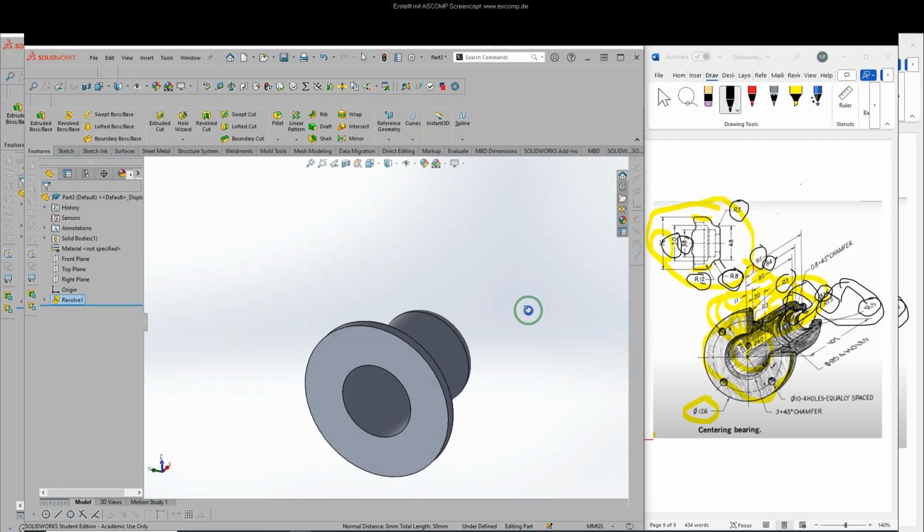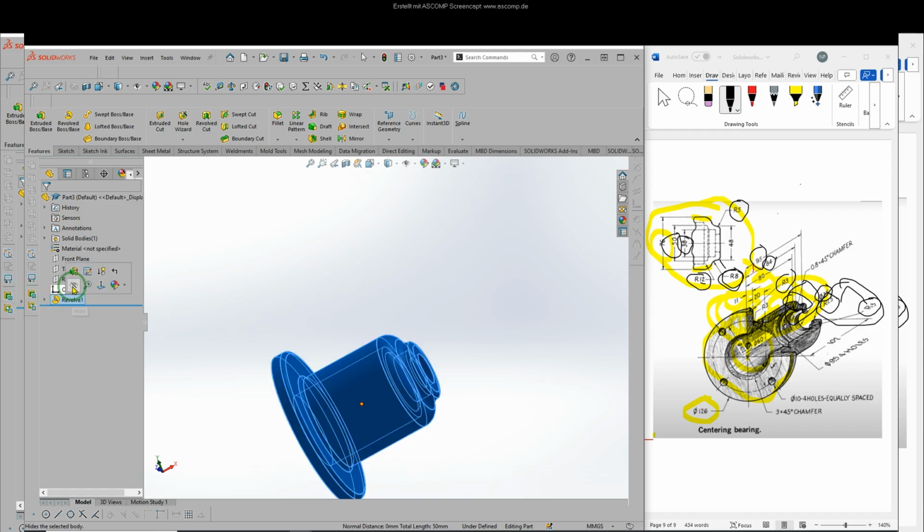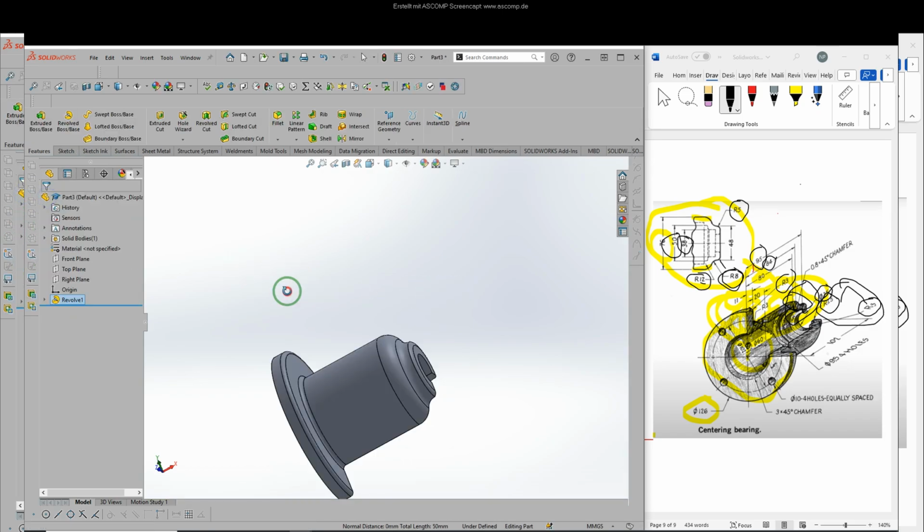You can see here, but in the technical drawing we can see this part is not given. So we revolved our sketch 360 degrees, but here we can see the sketch is revolved only 270 degrees. So here we enter a 270 degree angle for this space. Click OK.